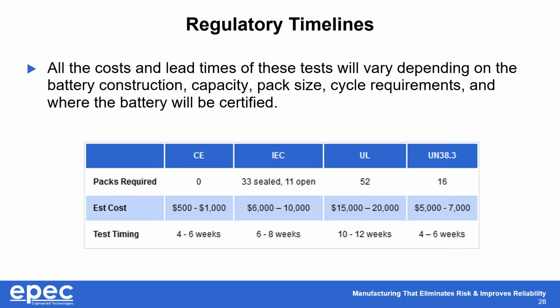The UL is obviously the most critical in terms of the amount of packs it takes and the amount of time and cost. And depending on what UL standards you're testing to, we have to know that up front, because we have to design everything in order to meet that specification, which also adds time to the design. Because we know there's certain requirements, especially around safety, the IEC and CE are sometimes needed. IEC more than others, but those certifications can be done laterally only after the 38.3 cert is completed and the design is locked down.